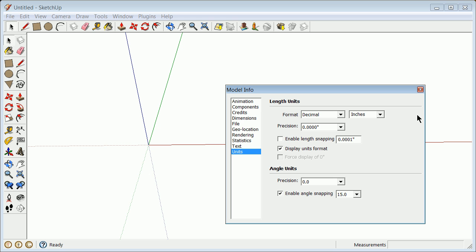For the surveyors out there, we can get into the discussion of survey inches at another time. One of the declarations is that when they moved from the metric system to the English system, 2.54 centimeters equals 1 inch. It is declared as an absolute. The other one that's an absolute, just so you know, is the declaration of a meter, which is now defined as the distance that light travels in the reciprocal of 2.99792458 times 10 to the 8th meters per second. So think about that. Look it up in your standards.